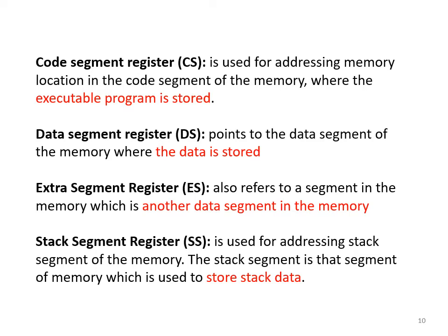So the address of that move instruction should be stored somewhere, so you are actually pushing it to a stack, and once that subroutine is executed, you will pop the data from the stack, and that address will tell you where your next instruction after the subroutine call is.